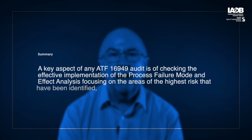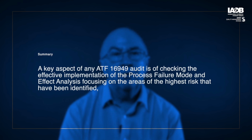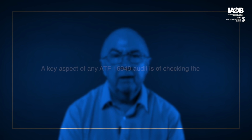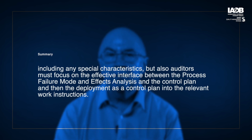So let's summarize. A key aspect of any IATF 16949 audit is checking the effective implementation of the process failure mode and effect analysis, focusing on the areas of the highest risk that have been identified, including any special characteristics. But also, auditors must focus on the effective interface between the process failure mode and effect analysis and the control plan, and then the deployment of the control plan into the relevant work instructions.